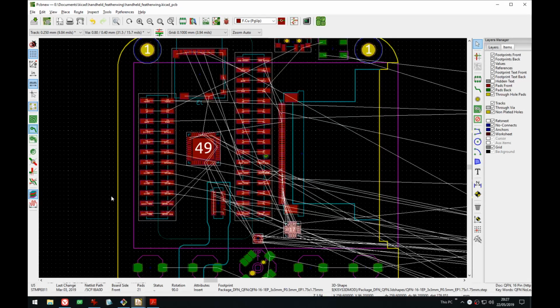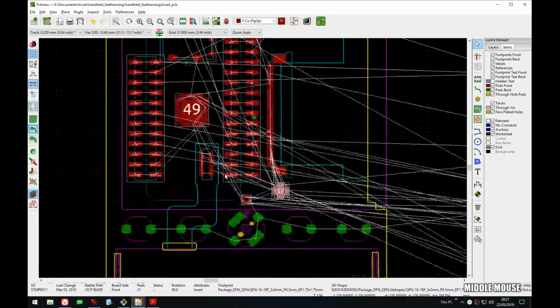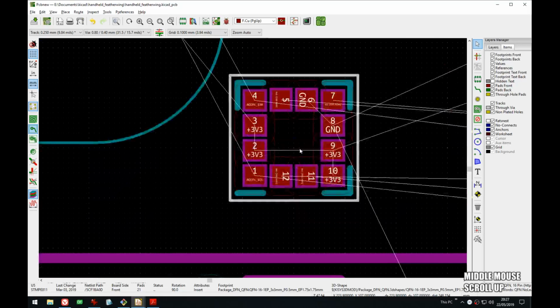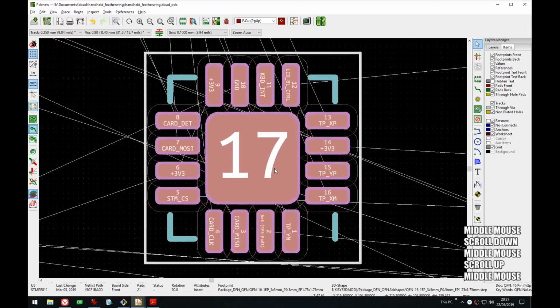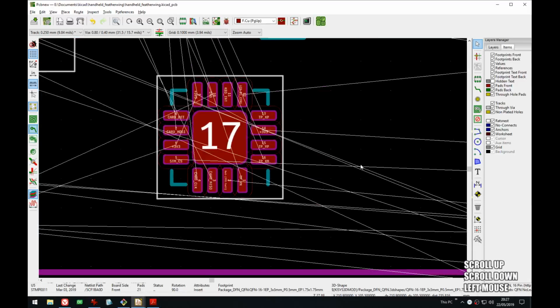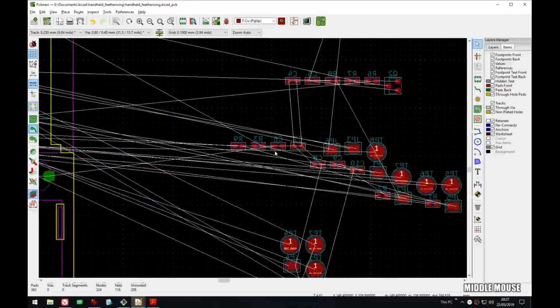So I'm trying to use things that they use so I have to do as little software work as possible. The accelerometer is I2C here. And it's SPI because they also use SPI, so I just wanted to copy those things.